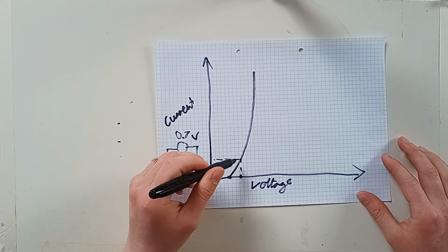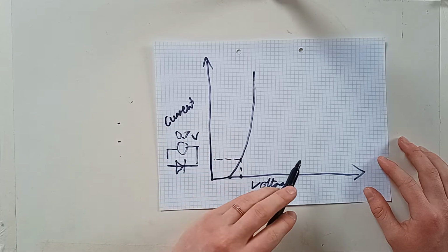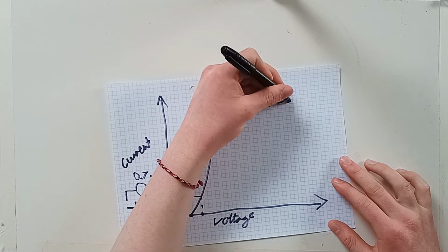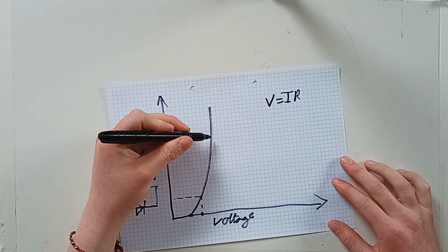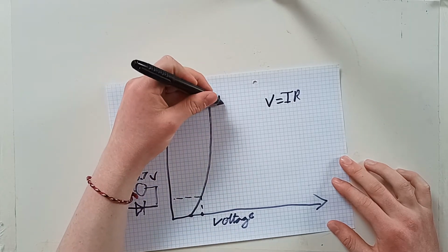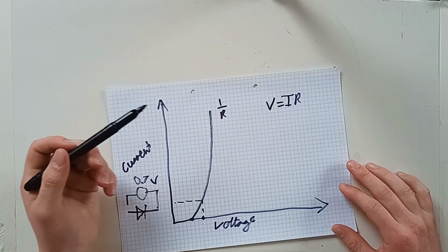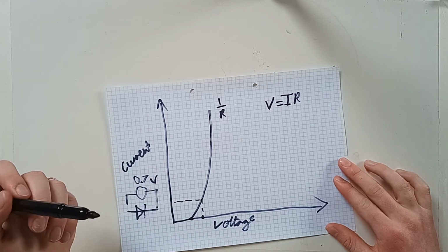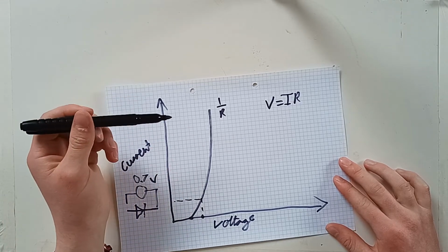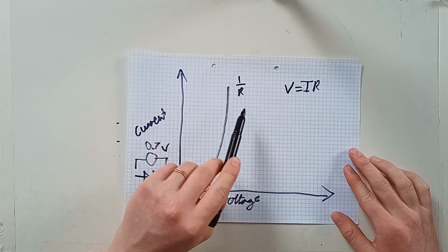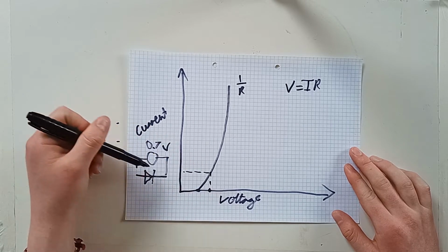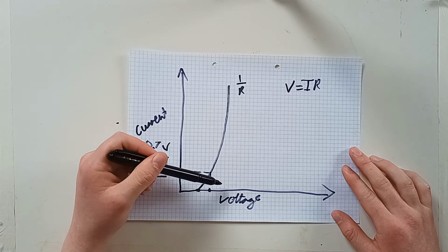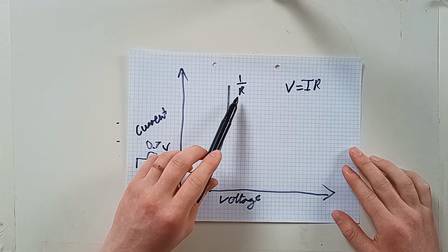which, using the equations for current and voltage, so your voltage is your current times your resistance. In this case, the gradient of this line is 1 over your resistance, as you are dividing current by voltage rather than voltage by current. So this basically means that as you increase this voltage over your diodes, there is a reduction in the resistance.